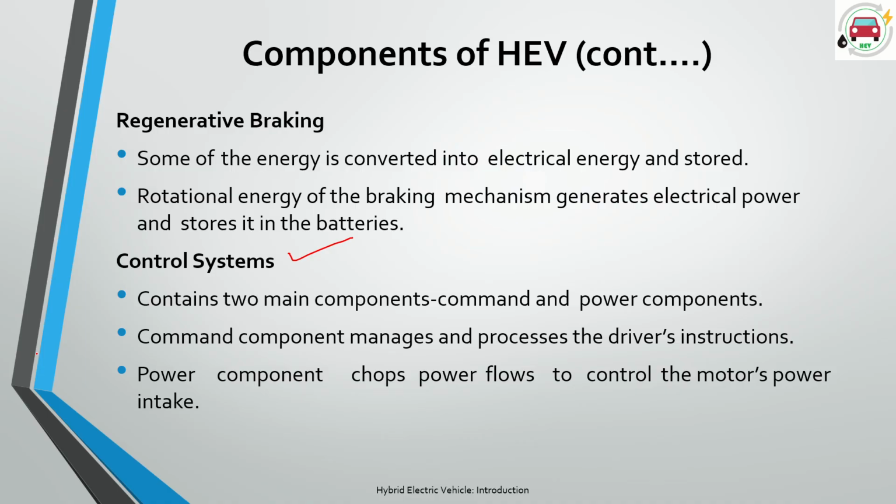Also the power component: how much power remains over there, and when we need to start the engine in the case of a series hybrid system, and in a parallel hybrid system, how much load should be given to the batteries, and how much load should be given to the motors or APUs, right?